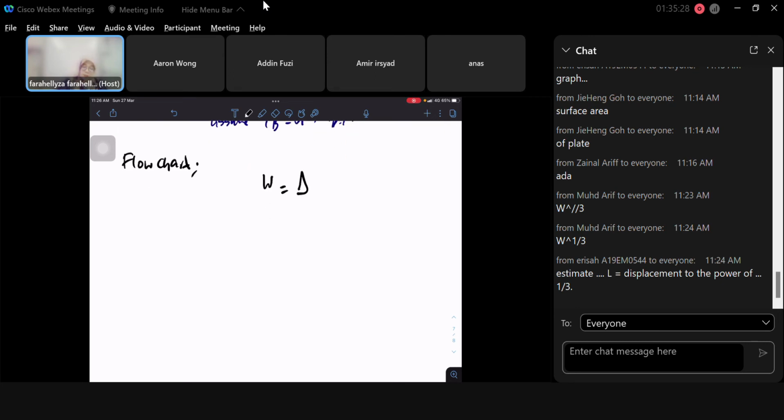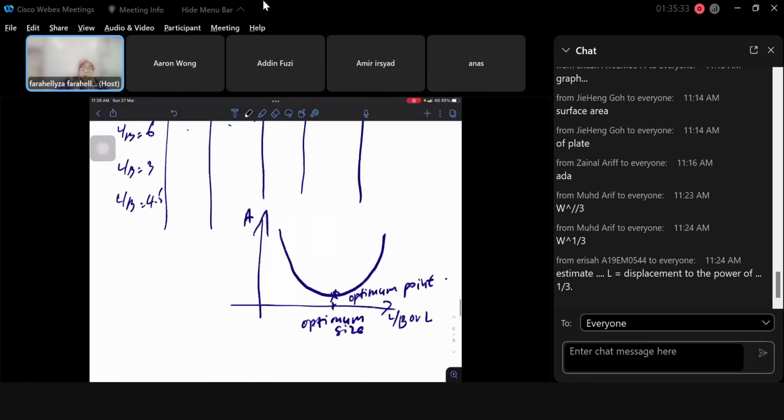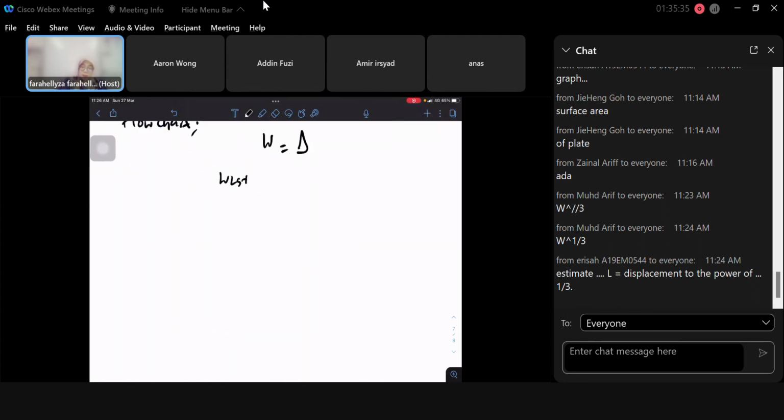Basically, if I want to expand this equation, so W_LS plus dWT is equal to rho times L times B times T times C_B. It's actually another thing, 1 plus S. Now 1 plus S is basically for the plating thickness. But sometimes we can neglect this one, 1 plus S.